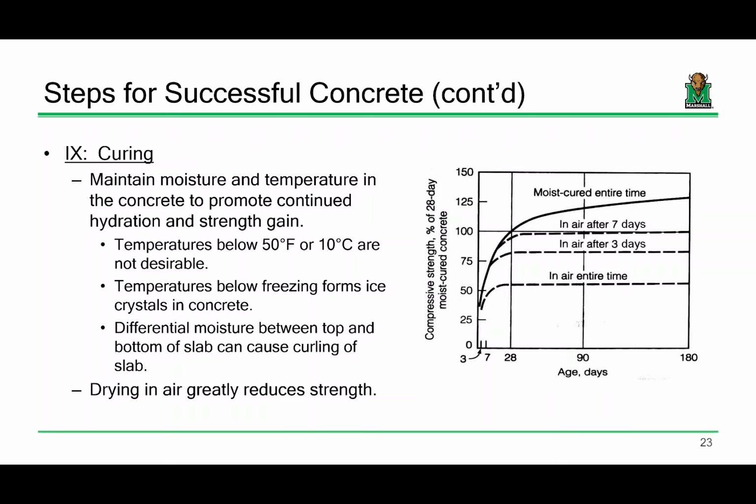And so the first few days are really critical to ensure that the concrete behaves well over its design life, okay? What we're interested in the curing process is maintaining the moisture and the temperature. It's one of the reasons why when we cast the mortar cubes, we put the sponge on top with the water, okay? Because we're trying to maintain the moisture inside the cube, okay?